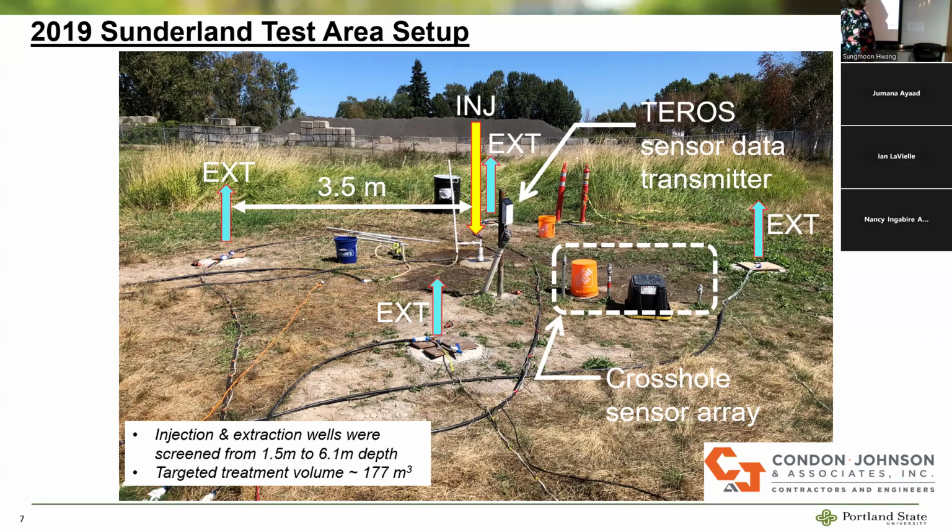There's also the monitoring systems we have set up at the site. This is an in situ array of moisture electric conductivity sensors that are installed at various depths in an auger hole. And then a seismic cross-hole array installed by the University of Texas folks back in 2019 to measure pressure wave velocities at various depths.